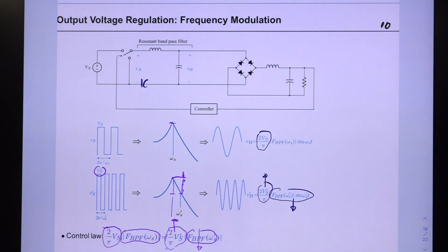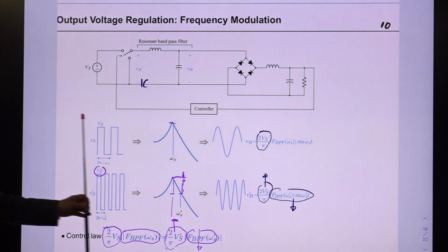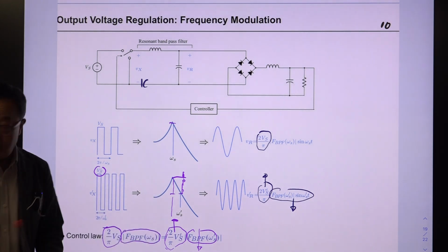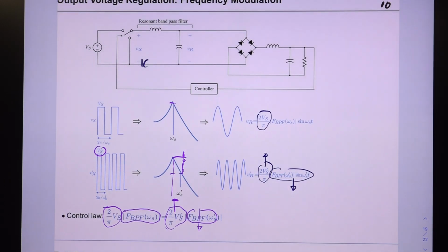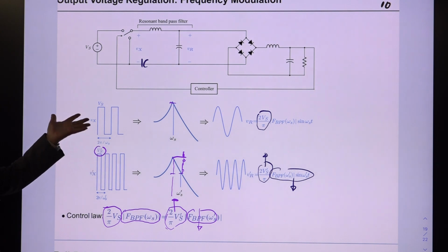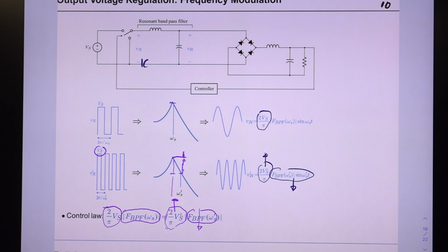So that is a big difference compared to the PWM converter. In the PWM converter, you play with the duty ratio of the converter. Now you have to play with the switching frequency of your converter. So it's called frequency control. That is the basic control mechanism for this. There is another mechanism. You can modify the waveforms of these pulse waveforms, but that is the secondary option. So the primary means of regulating our voltage is frequency control, which is very, very troublesome for some cases.